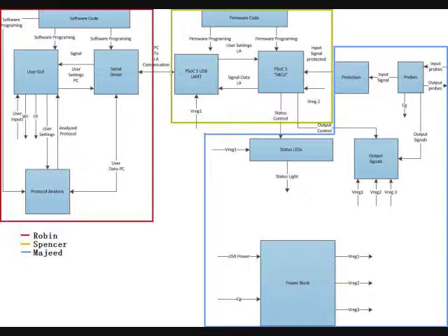It reads the input signals, gathers that data, and sends it to the USB UART section. It also takes data from the PC, transfers it through USB out, and turns that into status control and output control signals. The USB UART is a physical implementation over USB that is actually a serial port, and it's also in charge of encoding the data coming from the PSOC 5 and compressing it so throughput can be met.